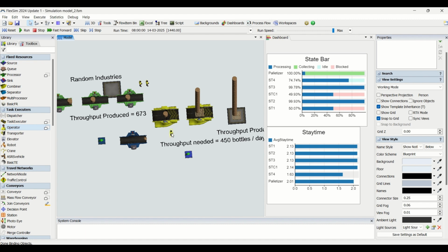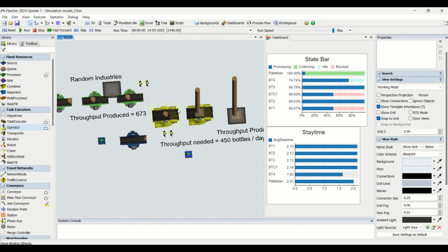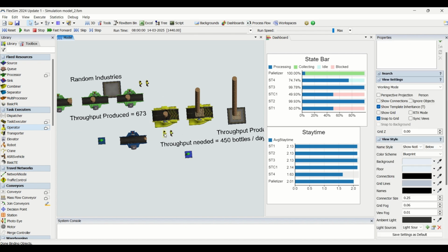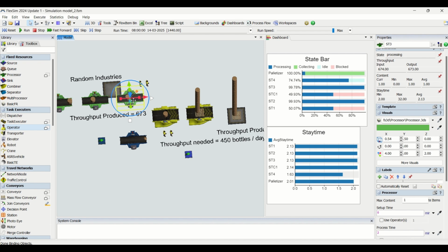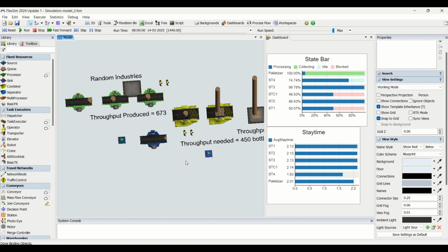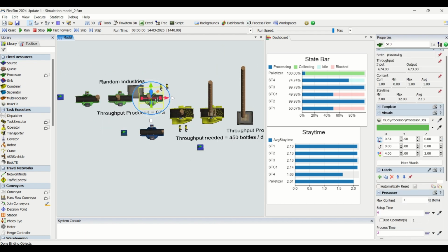But if you need to meet your targeted demand, you need to have additional 2 operators onto our station of combiner here as well, which will reduce the cycle time from 3 to 1.5. And then the operator from here will be shared with this for the extra 0.5 minutes, okay, which is going to make the cycle time for the particular station 2 minutes.